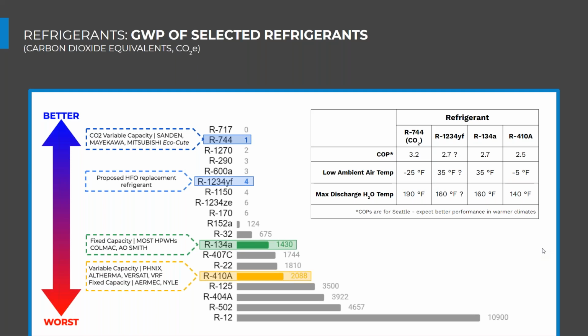During defrost is another thing we need to be conscious of, is these heat pumps aren't providing heat to the system. And so we need to be talking to our manufacturers, asking them how long that defrost cycle is anticipated to be, and then derate that capacity based on the duration of that defrost cycle. There's typically two ways to defrost a heat pump, active or passive.